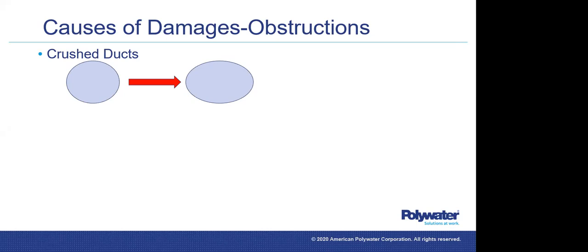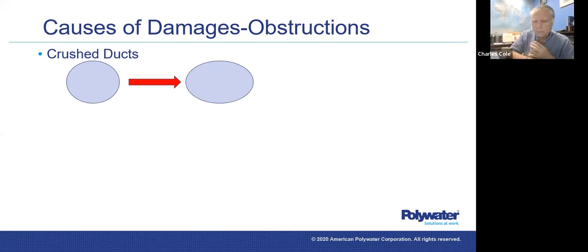There's really no simple solution to resolving this issue, but it's important that you not try to install a cable before proving the duct has shown whether there is an obstruction that's going to cause problems. So it's not simple to resolve this ovalization.